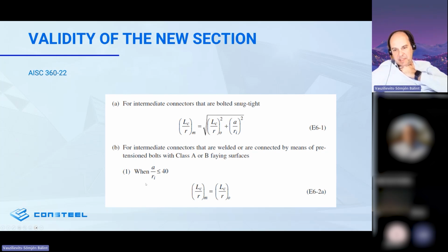But on the other hand, they say that the connectors must be equivalent to something welded or pretensioned. I don't believe that pretensioned bolts are used very often. This chapter of the American standard is not the one related to cold-formed sections, but the most general design standard for any sort of profile.